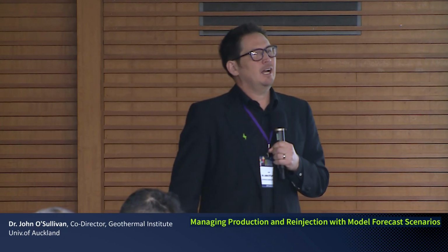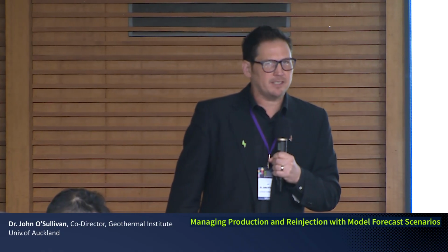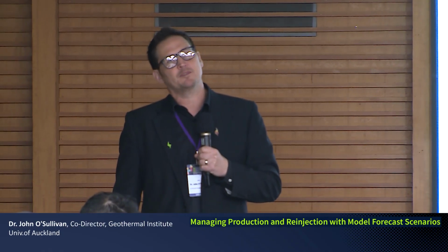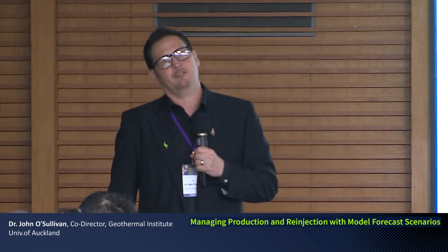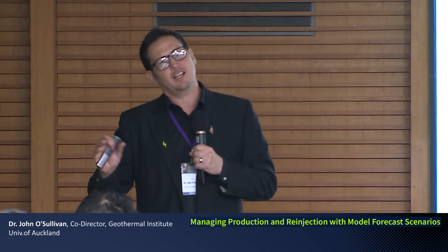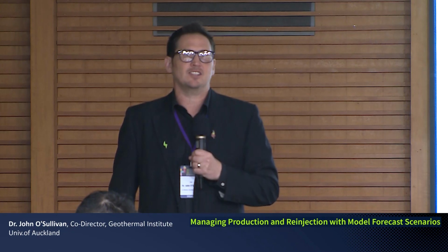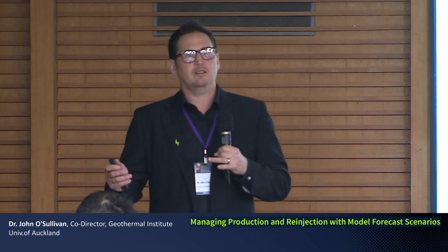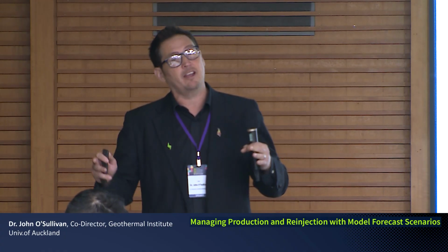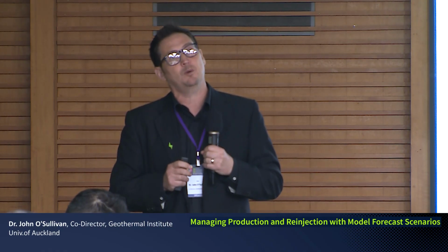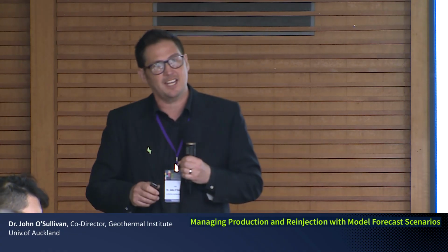So for a conventional geothermal system, the best practice is a porous media, but we often do porous media in a dual porosity approach where we are representing fast fracture pathways and matrix, where we allow some thermal non-equilibrium. The reason why that is the best practice is that to model and understand a conventional geothermal system properly, you need to model a very large area. You need to model all of that recharge and all of the full convective system properly, which just isn't practical with a DFN computationally at this stage.